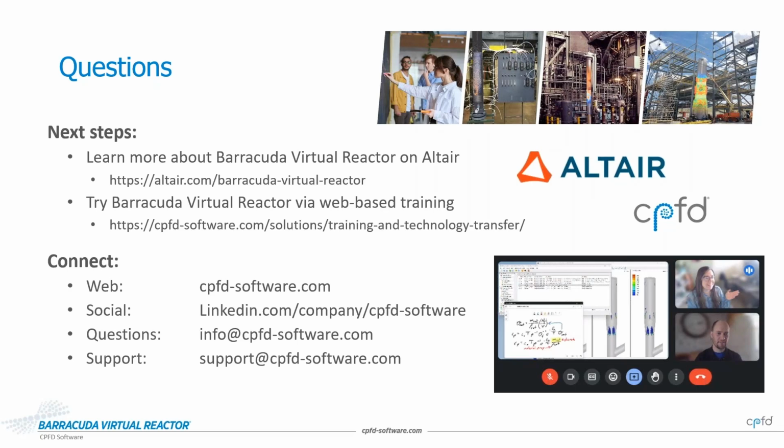When a particle hits a wall, now we do know the particle hits a wall patch, so we'll know the angle of impact, and so we can have a restitution and a scatter function that the user has control over as well. But the reason this matters is that using those models instead of directly computing does two things. It reduces the computational complexity tremendously, which lets us go to full industrial scale. The second is it doesn't require super small time steps for collision detection, which again lets us move much quicker.